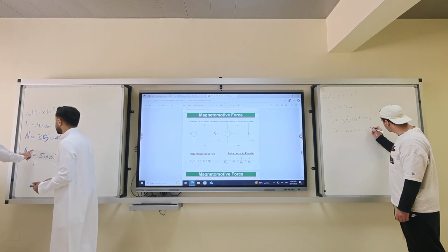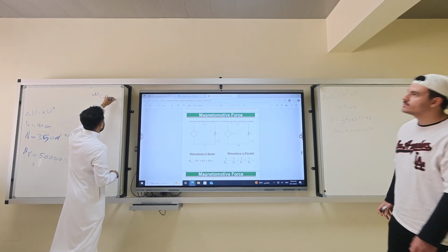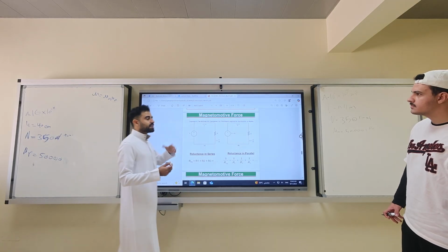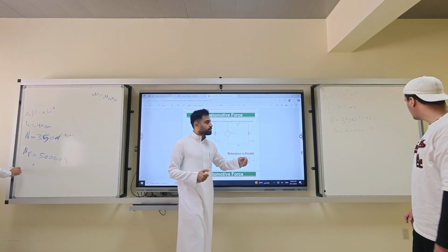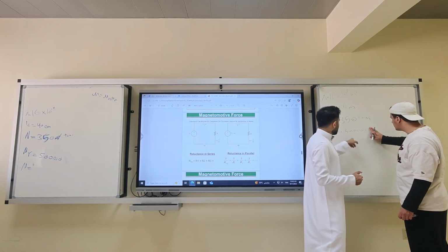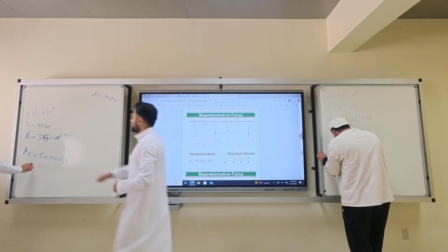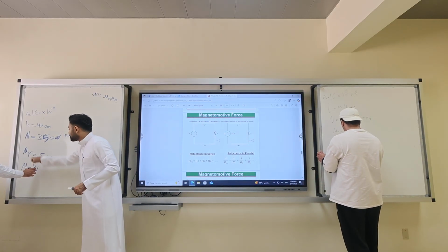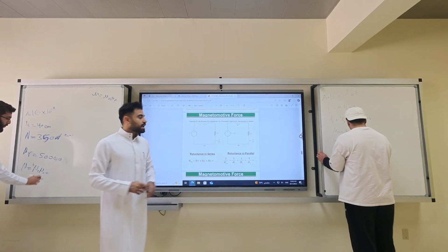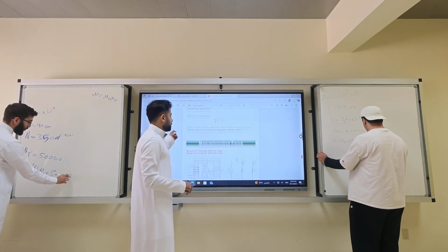What is the mu? Mu is mu naught times mu R. This has no unit, this has a unit. So just write it as mu naught, because mu naught is a number. No, this is mu R, 50,000. Mu equals mu R times mu naught. So it's 50,000 mu naught. And it has a unit of Henry per meter. Quick.